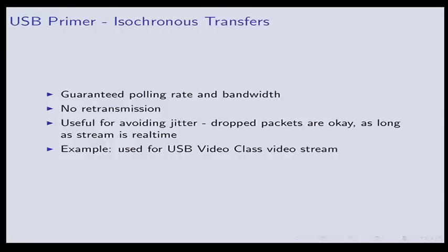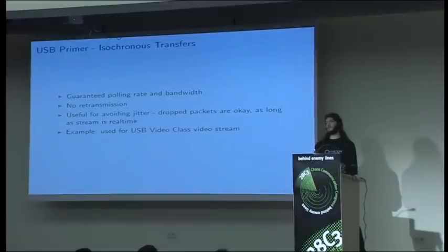And the neat thing about these is that they're guaranteed bandwidth. When the host sees that the device has an isochronous endpoint, then the host will allocate all of the bandwidth that that endpoint could potentially use when it tries to do scheduling of bandwidth on the bus.